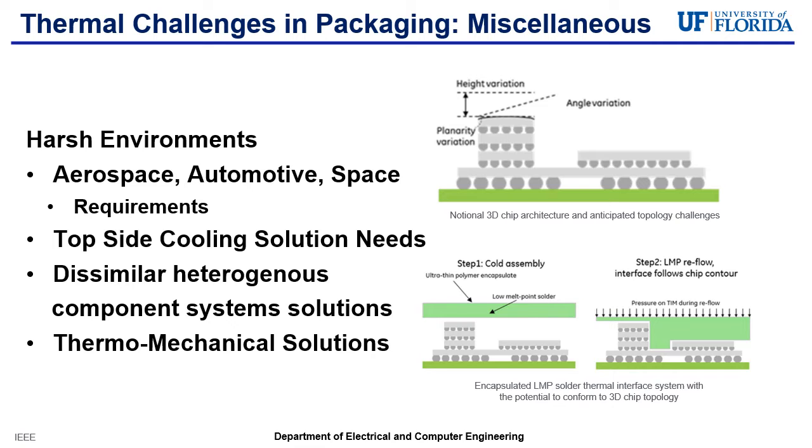This is especially important in high-power systems where the heat generated at the top of the chip must be managed effectively. Semiconductor packages in these environments also often contain dissimilar heterogeneous components, meaning they're made from different materials with different properties. Creating thermal management solutions for these kinds of systems can be complex due to the different ways materials react to heat. Thermomechanical solutions are engineered to address these challenges. They are designed to accommodate the physical changes that occur due to thermal expansion or contraction, and to ensure that the semiconductor continues to function correctly.